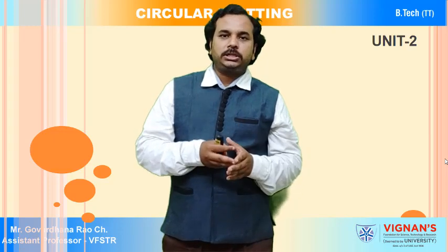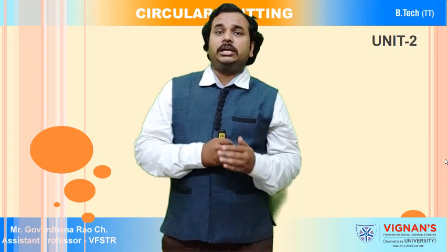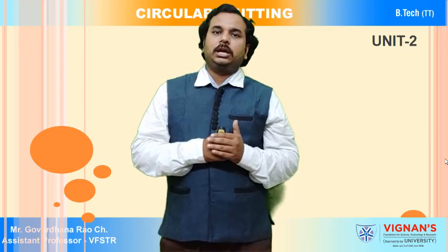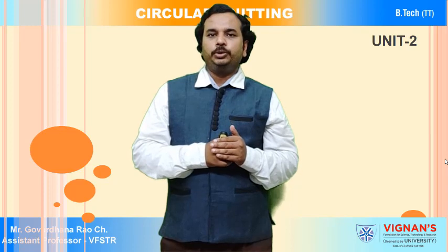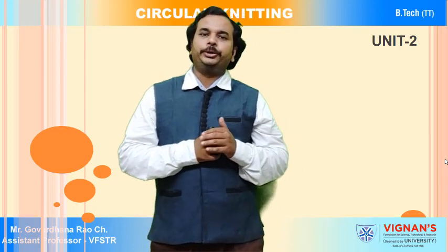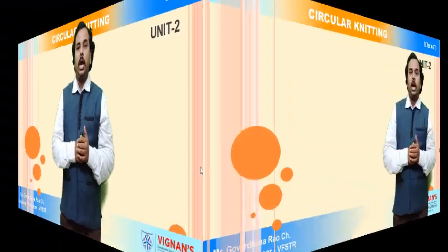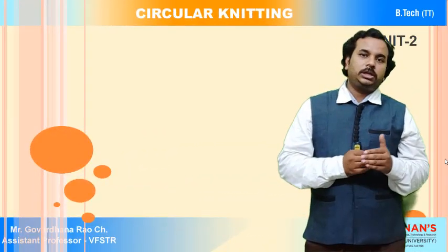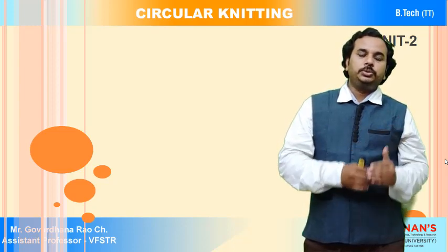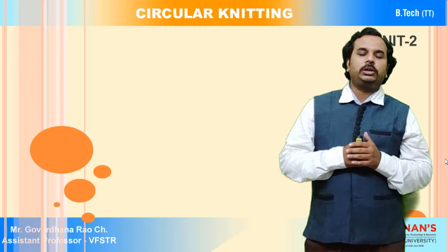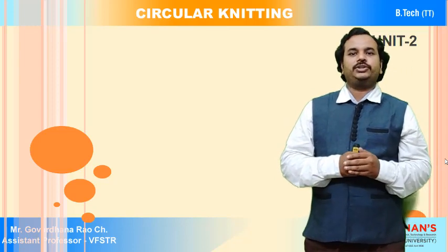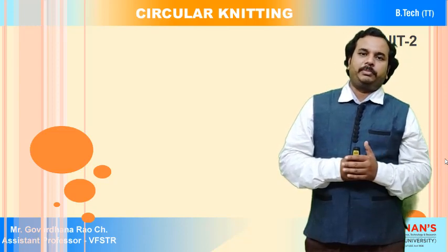Particularly, we discussed the slider type of movement and how the sliders and pattern sliders are used to select the particular type of needle to produce different stitch effects. We also discussed the pattern wheel, which is used to produce motifs or to get different stitches in the knitted fabric structure.